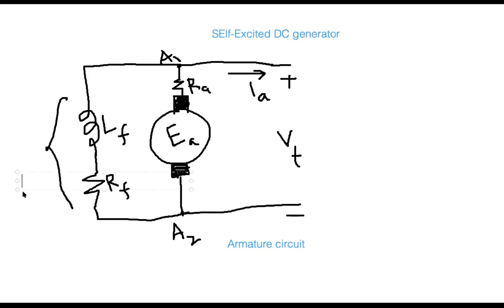Let me write down at the beginning, then you will be fine. This is your field circuit. So therefore, you see, what is the source, how is it getting powered? There is no extra source now. It is fully dependent on this voltage, or the voltage initially that is being built up, developed. It depends on that. So this means that the same voltage VT here appears across this one. Accordingly, it is called self-excited.